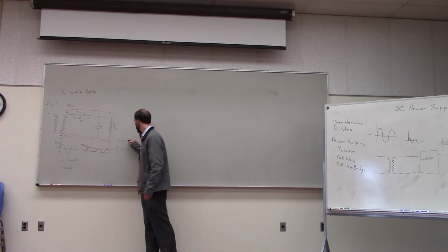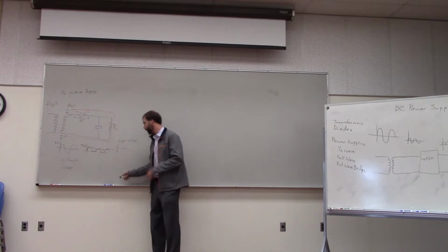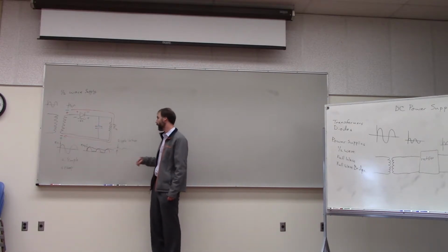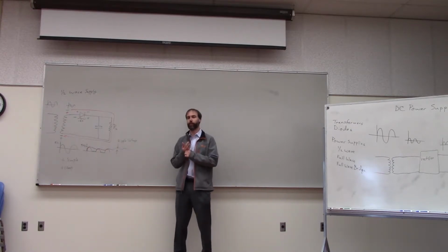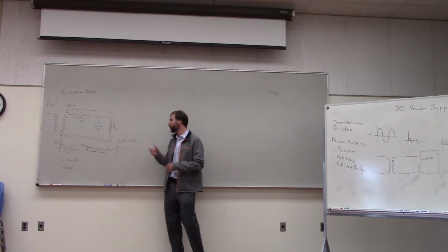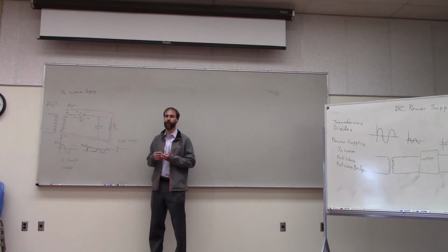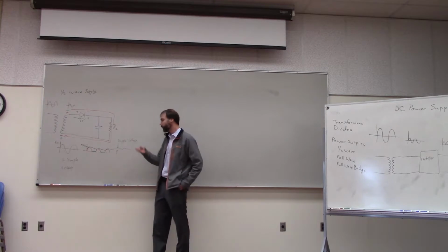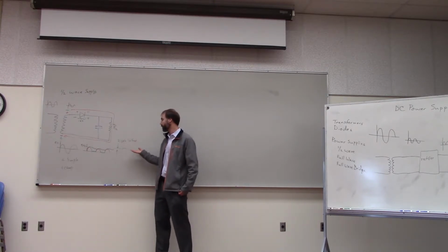So if you have a bigger capacitor, you get less ripple voltage. And that's what you want. Now there's always a trade-off, right? A bigger capacitor is more expensive and it takes up more room. So that's why you don't just put the biggest one in every power supply. But to go back to your question before, you were asking when or where these might be used.